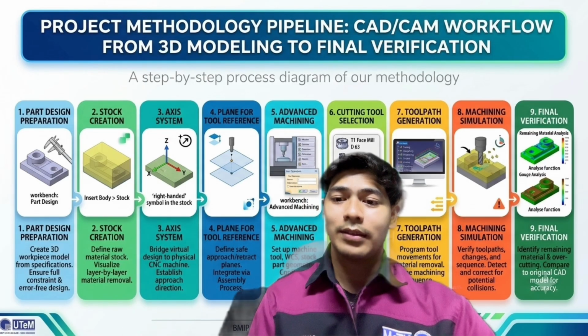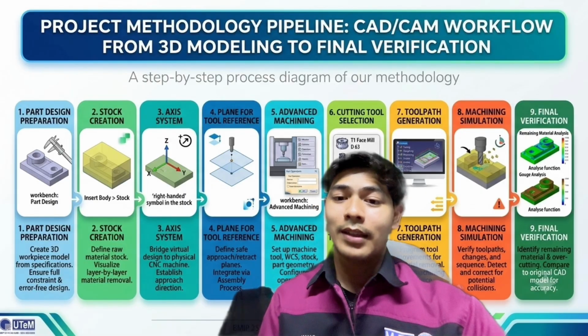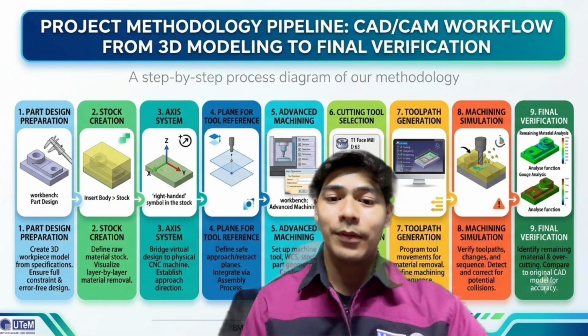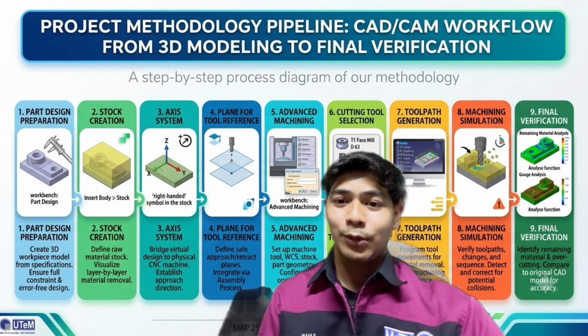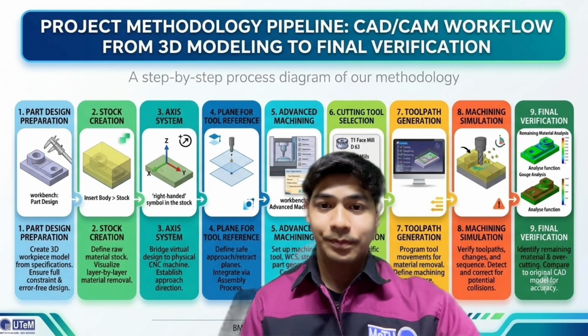And for the fourth step, we create the tool reference plane in a separate part design file. This plane serves as the approach and retract position for the cutting tool. An axis system was also defined on the plane before assembling them with the workpiece using the assembly workbench. This ensures safe tool movement during machining.